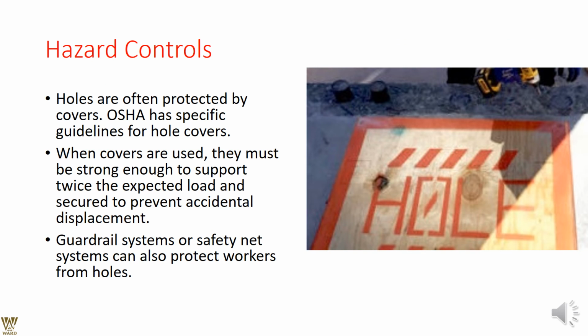We'll talk about hazard control. What do we have? It's the way you cover a hole. That needs to be done. So there are no chances: if you have dug a hole, if there is a drilling in place, always at the end of the shift cover the hole and fasten it down, so it doesn't get loosened in any way. The covers must be strong enough and are expected to take load twice the amount that goes around it. This will enable you to prevent any sort of accidental displacement, any sort of accidental fall.